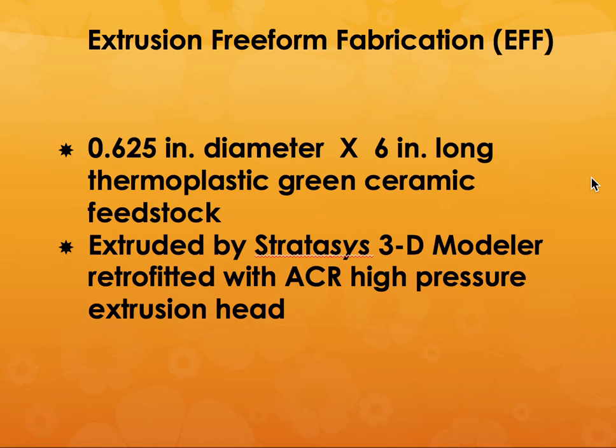Again, I'm going to talk more about extrusion freeform fabrication. I will probably post a paper about fused deposition of ceramics, one of the earlier papers, for all of you to take a look at. In extrusion freeform fabrication, we have an extrusion head into which we place a feedstock about 6 inches long and approximately 3/4 of an inch in diameter. We came up with a high pressure extrusion head and adapted it to the Stratasys 3D modeler that you may have seen, which is something similar to the MakerBots. So you are extruding the material from a feedstock bar rather than a feedstock filament.